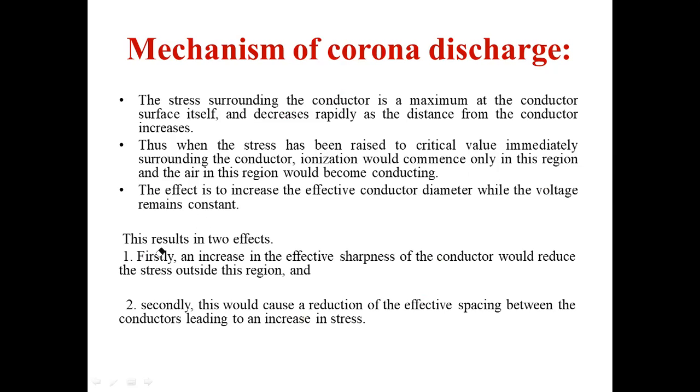So this results in two effects. Firstly, an increase in the effective sharpness of the conductor would reduce stress outside this region, and secondly, this would cause a reduction of the effective spacing between the conductors, leading to an increase in stress. Okay.